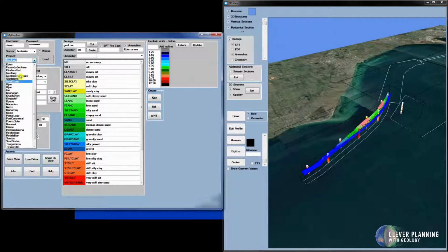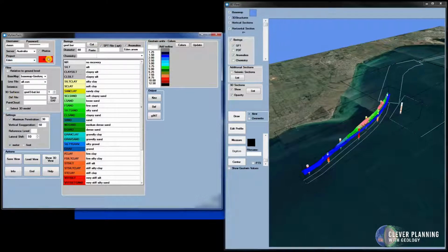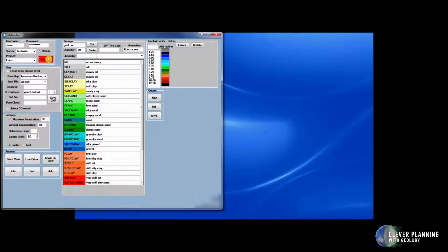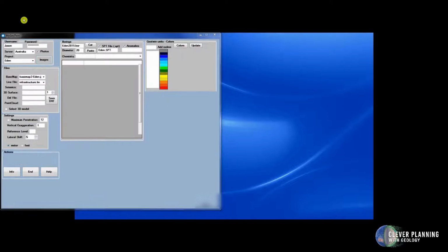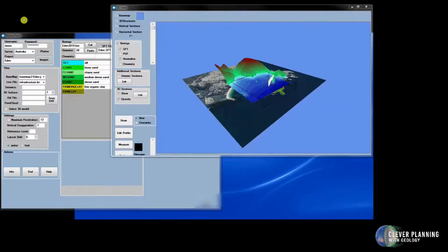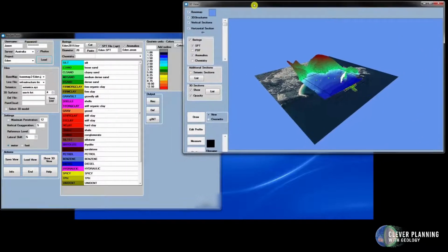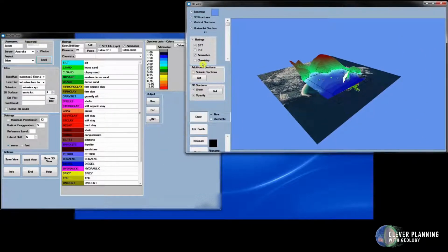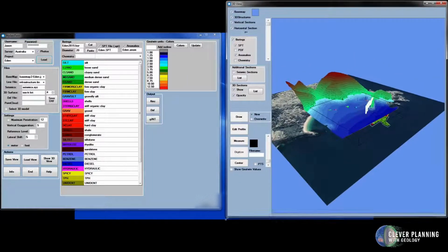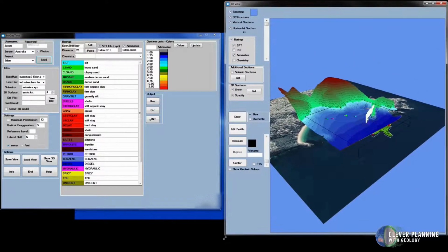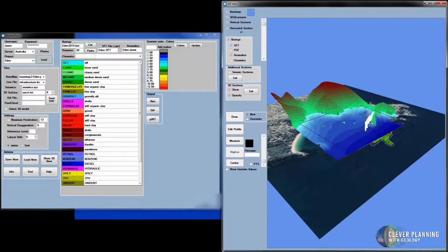A geology digital twin was also made for the Eden Port development. Approximately 14 line kilometres or 1.2 million data points to 12 metre penetration were collected in just a day. Using this model, we will import the Advanced Geophysical Point Cloud, import and work with construction alignment as a DXF, create and work with vertical and horizontal sections, measure and use the settings, and get familiar with boreholes.